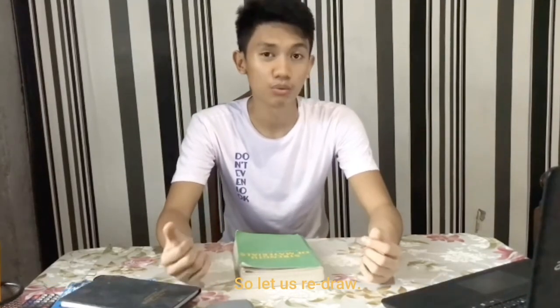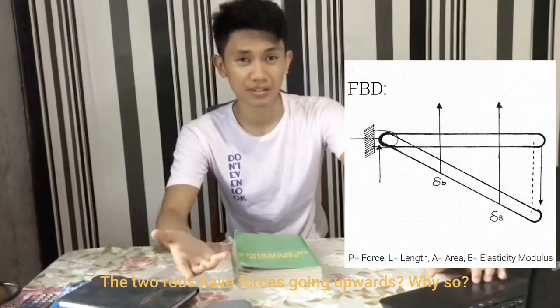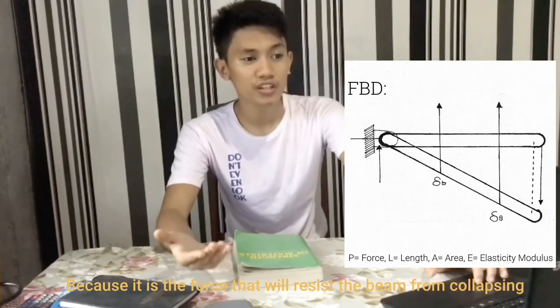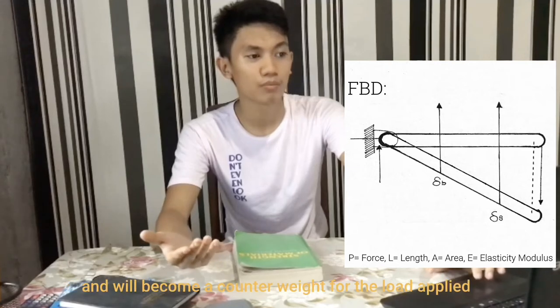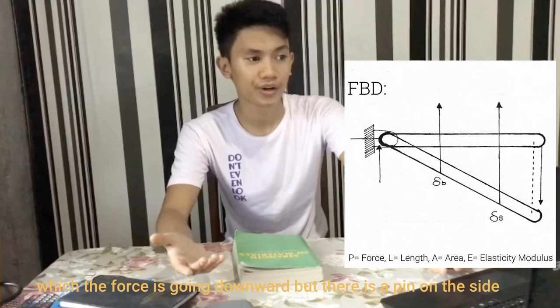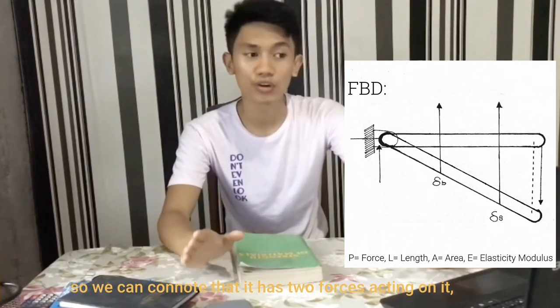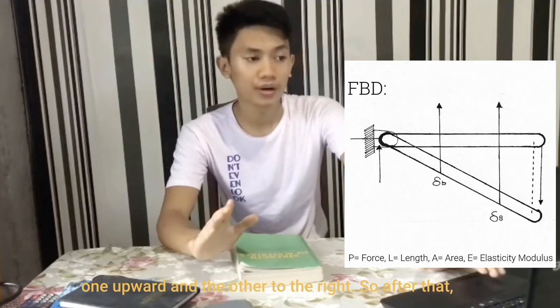So let us redraw. The two rods have forces going upwards. Why so? Because it is the force that will resist the beam from collapsing and will become a counterweight for the load applied, whose force is going downward. But there is a pin on the side, so we can say that it has two forces acting on it, one upward and one to the right.